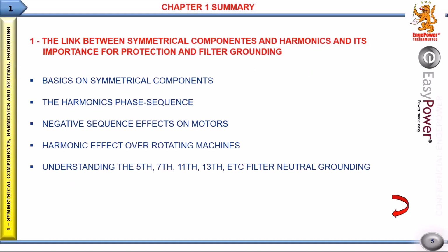Chapter 1, here is the summary of the topics we are going to talk to. Basics on symmetrical components, the harmonics phase sequence, negative sequence effects on motors, harmonic effects, overheating machines, understanding the 5th, 7th, 11th, 13th, etc., filter neutral grounding. Most of you have already studied symmetrical components.